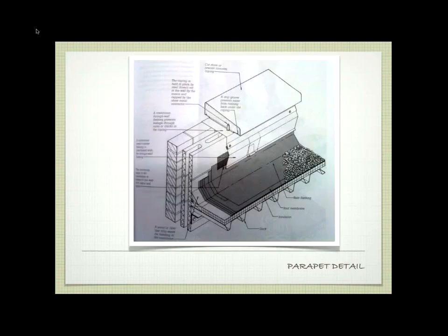Okay, this is a parapet detail. This is if the wall on the outside of your building extends above where the roof is. So this is the opposite of residential; it tends to be for commercial buildings, where we have this little parapet. Same concept here, where we need to make sure we pull the roofing up the side of the wall. Notice that there's always a 45 piece of wood in here, so that we don't have a tight joint.